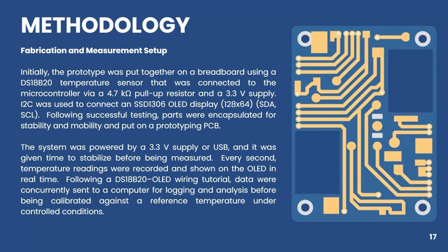Following successful testing, parts were encapsulated for stability and mobility and put on a prototyping PCB. The system was powered by a 3.3 volt supply or USB, and it was given time to stabilize before being measured. Every second, temperature readings were recorded and shown on the OLED in real time.